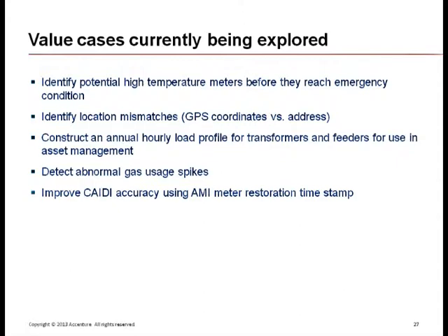So for this one, we are using transformer to meter connectivity model and feeder to meter connectivity model to determine transformer and feeder load profiles. One thing which needs to be mentioned here is the feeder to meter connectivity model which we are using is as designed, it's not as operated.